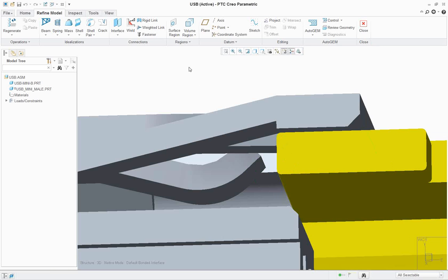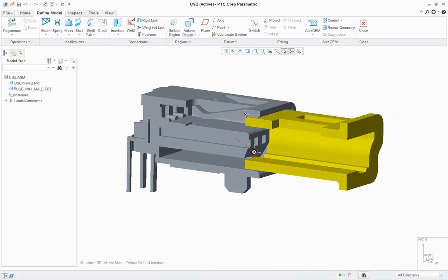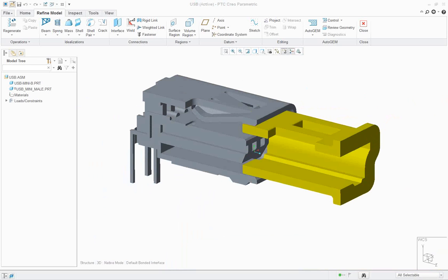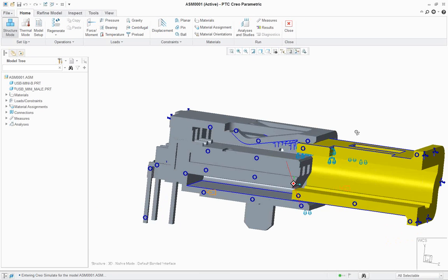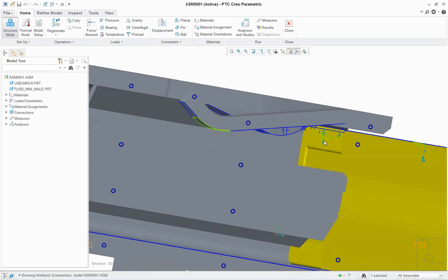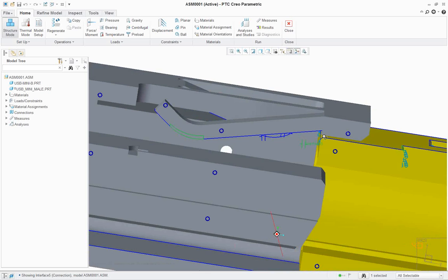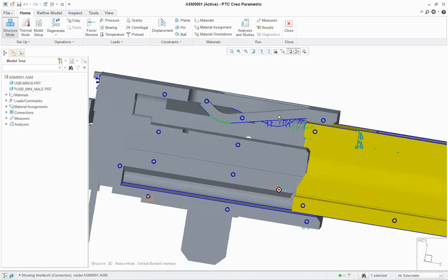Now, in this case, what we ended up doing is we have a model that's already been completely set up here, and if I go to that, okay, so this is the model that's been completely set up, and really the only thing is, we've gone through and defined all of the different surfaces that could potentially bump into each other. So for example, all these other surfaces at the bottom here that could potentially bump into each other, we've defined all of those contact interfaces.